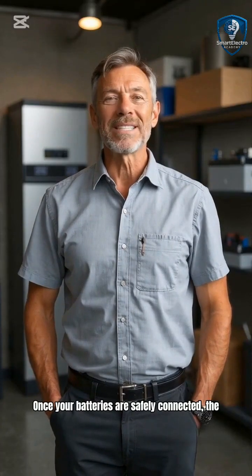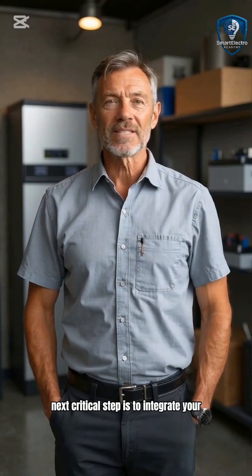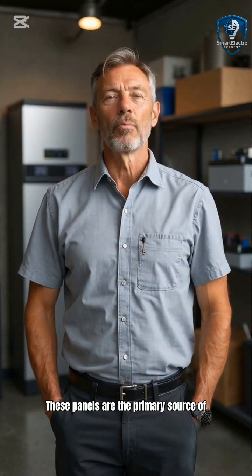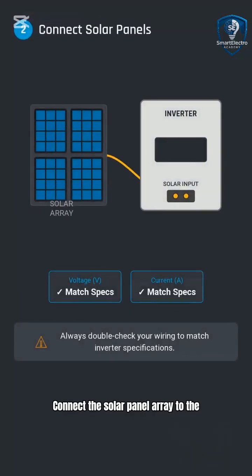Once your batteries are safely connected, the next critical step is to integrate your solar panels into the system. These panels are the primary source of energy generation. Connect the solar panel array to the inverter's designated solar input terminals. Always double-check your wiring to match the inverter's specifications for voltage and current.